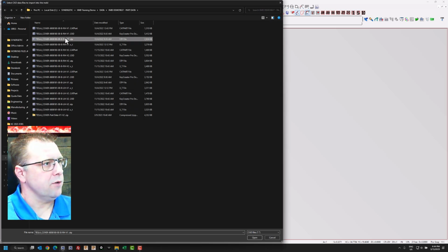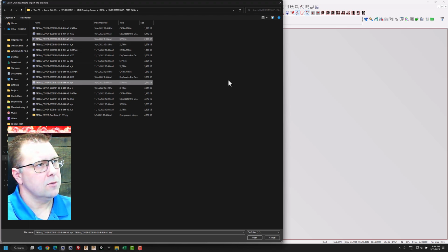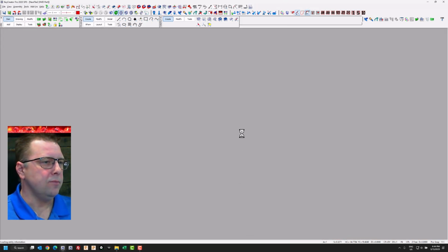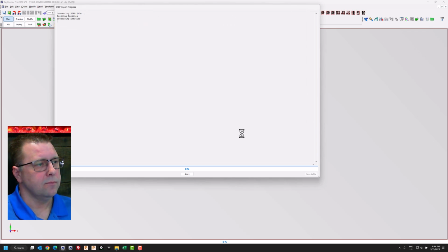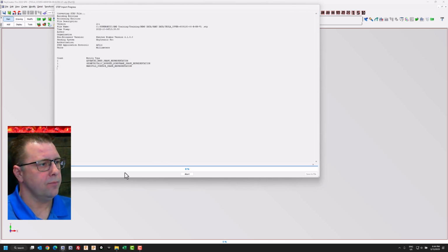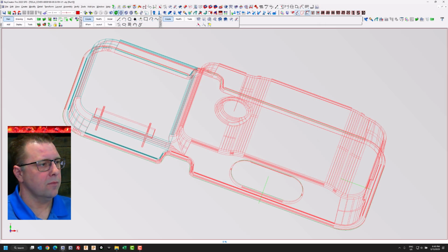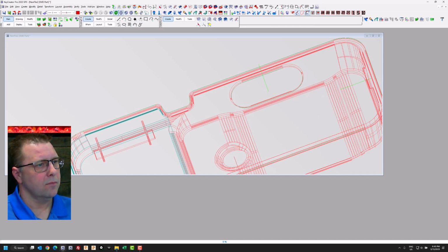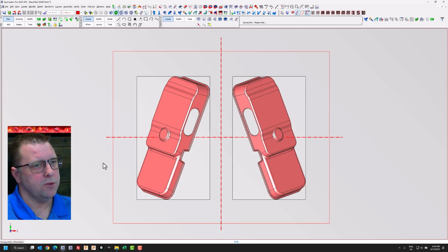We're going to pick our first version of the part, so we've got these V1 parts. You can import any file type you wish. And of course you pick all the part data at once. You're not limited to have to come back and reselect a second cavity. If you had 20 cavities, all different parts, maybe a family mold, you would select all of those right now immediately. We're going to let that import. So it's doing some processing right now.